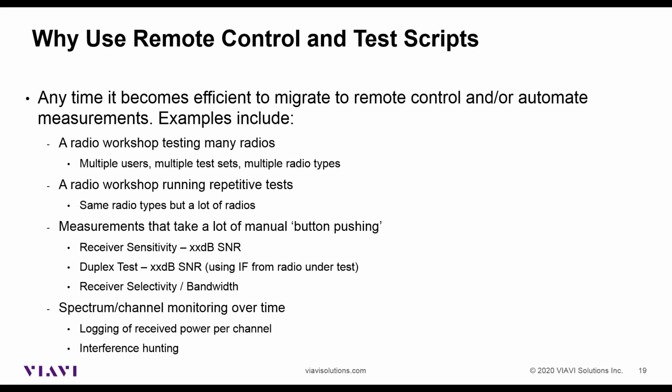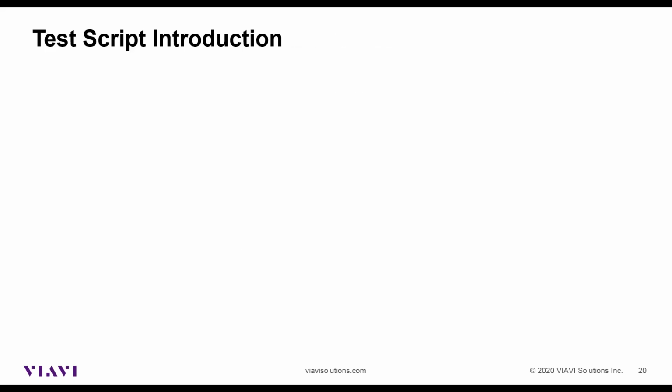And in terms of spectrum and interference hunting or monitoring, again, just have the test set reporting. You could be reporting broadband power, you could be grabbing spectrum traces over time. All of this is there for you to use, and let us know if you're not sure how to do this. We'll help you.